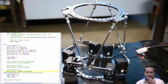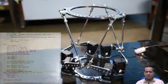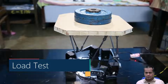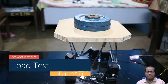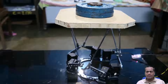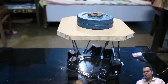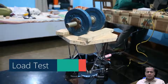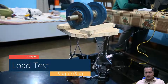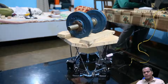This is the GUI and the coding environment, which is very much like Python, that can be used to control this. What you see now is it getting load tested with a 5 kg payload, almost 4 kg plus this wooden weight and 0.5 kg additional. This type of load testing we did to check what the behavior of this particular platform would be. This is exactly 5 kg plus. So this is how it was tested for load. If it is designed for 5 kg, it should work for 5 kg.